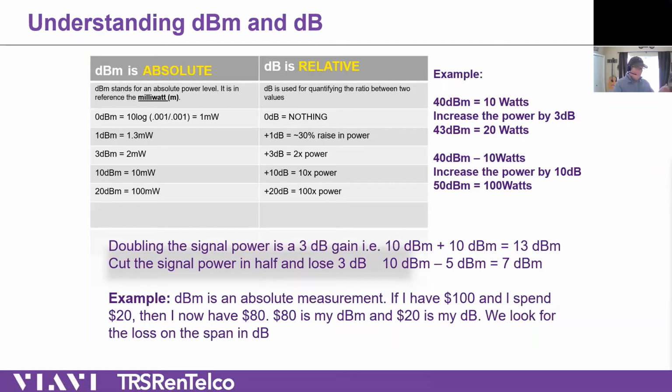So if I want to characterize my network, I want to test my fiber, I honestly don't care what the input power is or the output power, because that's the end devices. I care about how much loss my network is going to incur. So when Cisco shows up, for example, you can be certain that no matter what power you put through, I'm only going to lose 2 or 3 dB through there, and it's going to come out the other way.